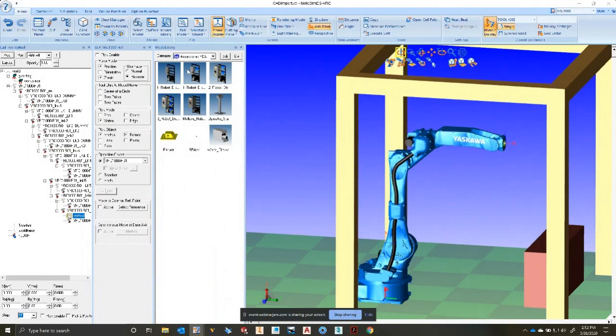It looks like a pile of junk on the floor. That's because the controller and the virtual pendant that you saw earlier and the main screen are actually two applications talking to each other. The network lag can cause a miscommunication. Just simply close the simulation. Don't save it, just close it, and copy it to your hard drive, reopen it, everything's fine. So make sure your simulations are running from your hard drive, but your model library can be on a network where you can share it with your coworkers. So moving on,